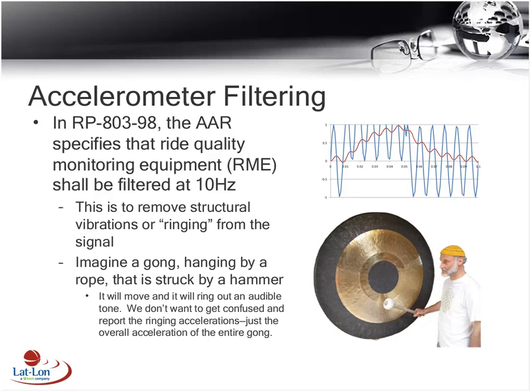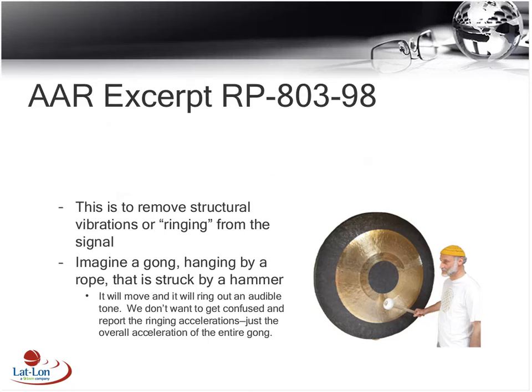And so you can see the red curve, which is the filtered signal at 10 hertz, it's got a better behavior for taking digital sampling so that we can reconstruct the event rather than just having data points all over the place.